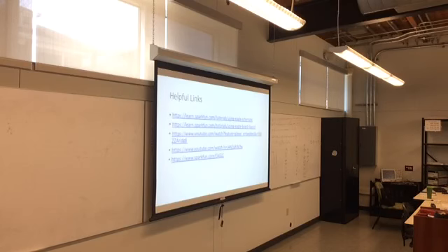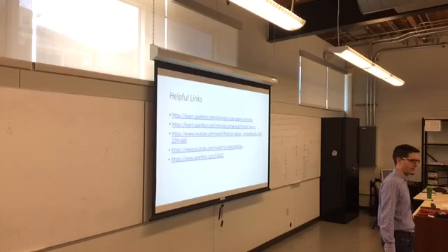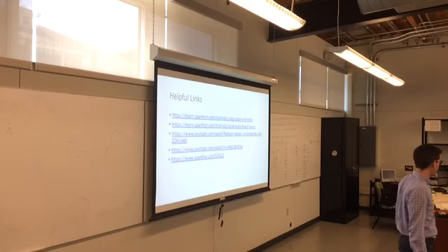So not a hard thing. Take your time. It's tedious. You've got a schematic and a layout. The schematic is the logical connections. The layout is physically how those things are routed. It's through-hole components that you can solder on like you're used to. It's surface mount components where you put some paste on the board and use a heat gun or a toaster to put them down.